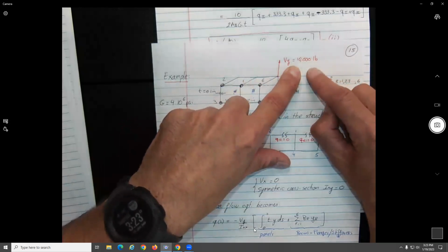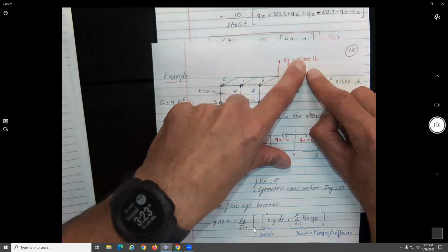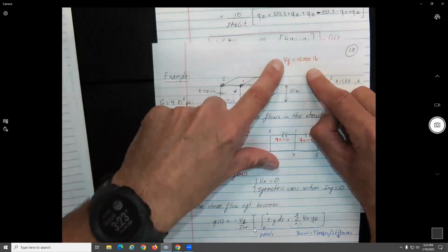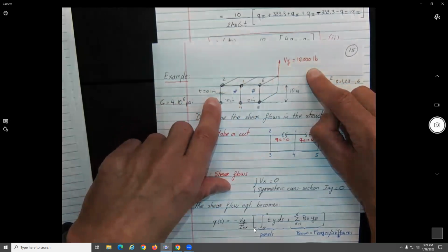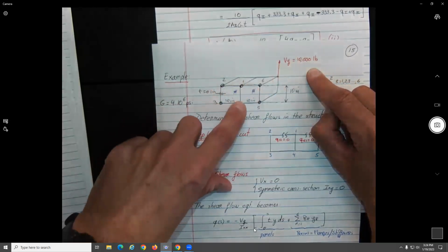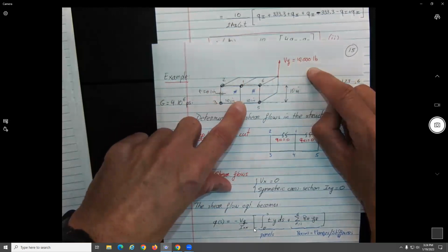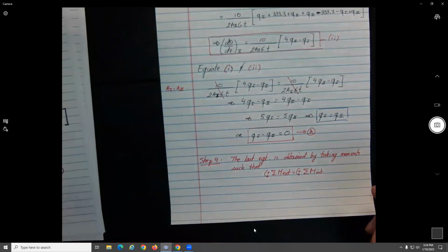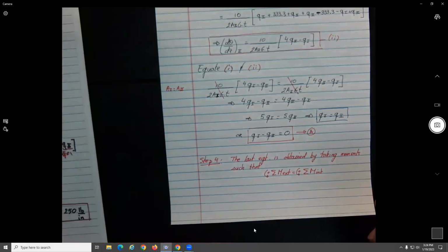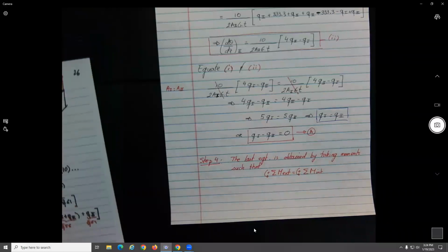All the effects that are happening due to the shear should counter-react the effect of this force. So what we can do is take the moment created by this force about a point, and say that it must be equal, because it needs to be counter-reacted by the moment created by all the shear forces inside the two cells. That's basically what we're doing next. Let's see about which point I did it. I probably did it about point 4, yes, about half.